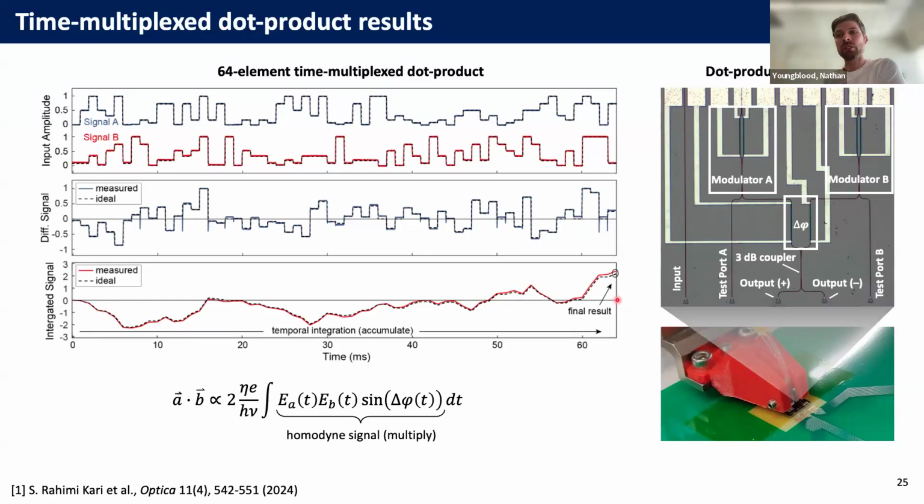This is something that we haven't really looked into very carefully. We've just assumed that we're limited by the resolution of the shot noise, both photonic and electronic, in terms of the theory. But in terms of practice, you're never going to be able to precisely set the amplitude and phase exactly, and there's going to be some sort of error that accumulates along. I think that ends up being a random walk, and so I think it's proportional to the square root of n, where n is the number of your samples.